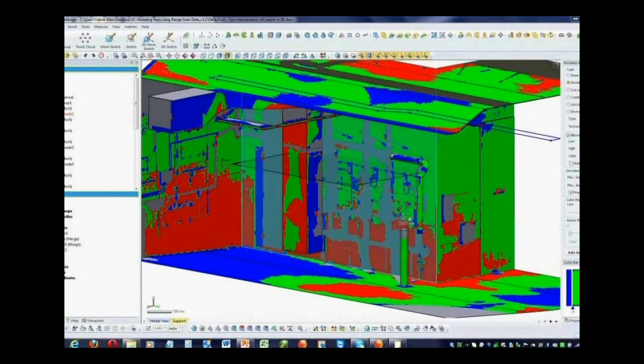The mesh buildup wizard is capable of triangulating from multiple point clouds, so it's like a batch process. You can align and then triangulate all the meshes together. And then we have a rewrapping functionality, which also closes open holes in the mesh and repairs triangles. That is one method to generate a very good mesh.